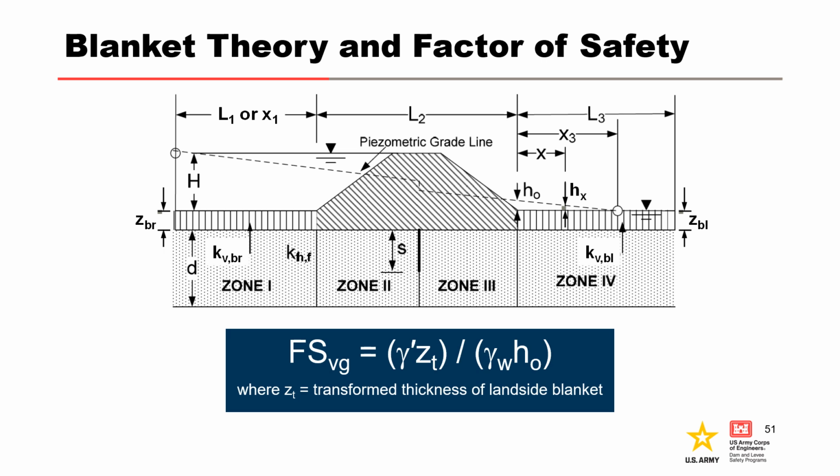Blanket theory has its origins in the method of fragments and other well-established groundwater hydrology solutions that were developed in the early part of the 20th century to facilitate solution of the Laplace equation. On the basis of this solid theoretical background, blanket theory has been used by the Corps of Engineers for more than 65 years as a practical means to calculate flows, hydraulic gradients, and pore pressures beneath levees. Results from blanket theory have been successfully incorporated into the design and evaluation of many levees along the Mississippi River and tributaries and other locations.